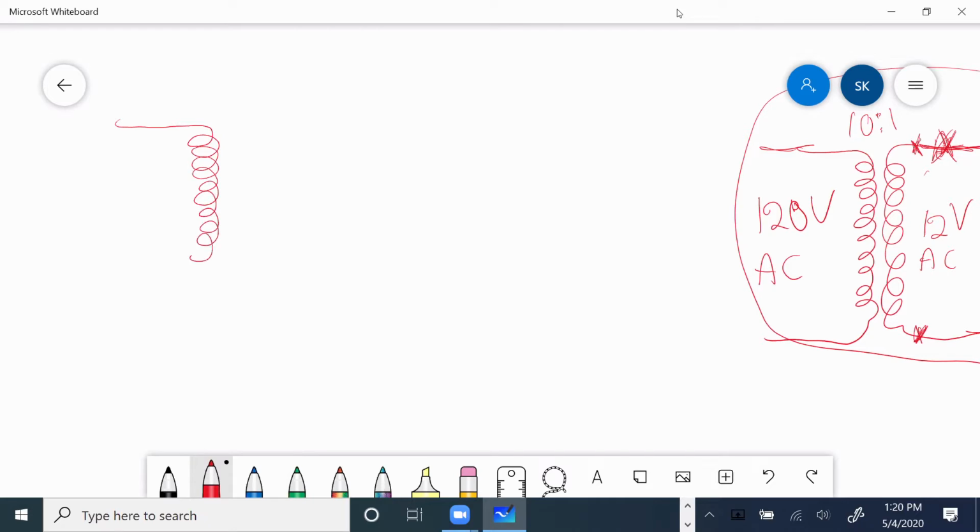Okay, before I go into two diodes, let me just come back and check if everybody understood what I said. Is everybody happy with the half-wave rectification? Very good. So with one diode, I can get only the positive excursion, only the positive side. For the negative, I get zero. I get no voltage.